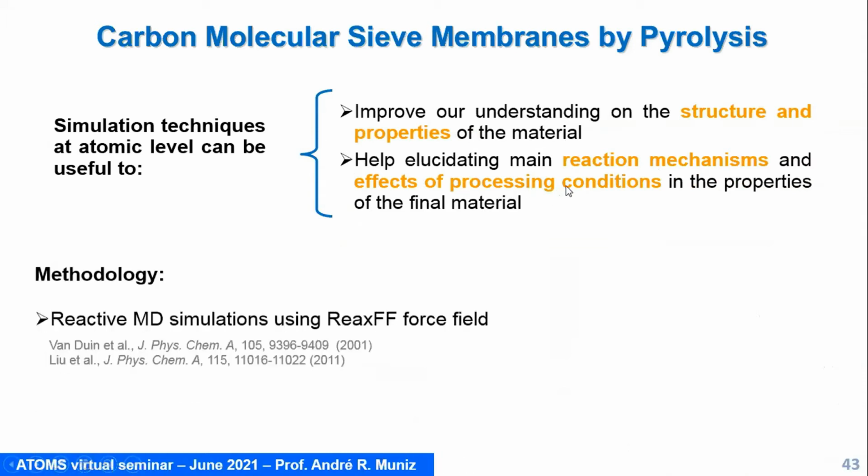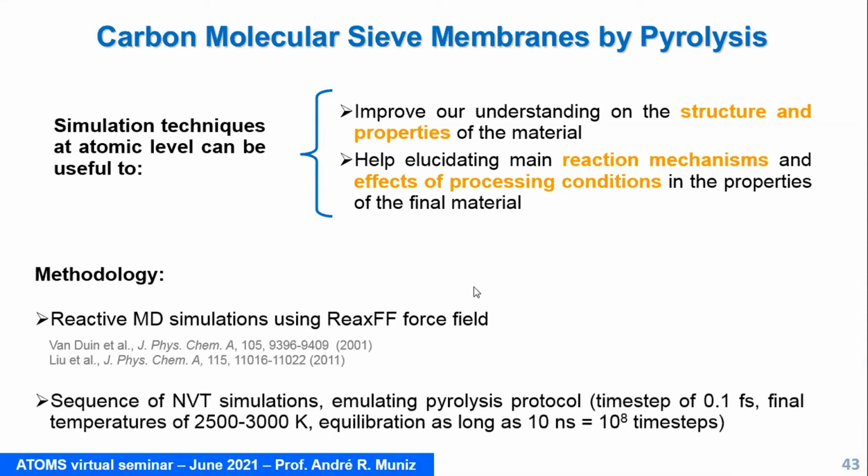So in terms of methodology, we use reactive MD simulations using the ReaxFF force field. It's a force field that allows the description of formation and breaking of chemical bonds. We use the parameterization that was developed for the degradation of nitrogenated organic materials, the closest that we could find for our material, with very good predictions.